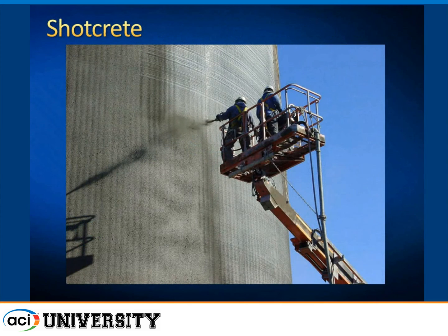In this particular case, it's being used on a tank to encase wires. But basically, Shotcrete is pneumatically conveyed concrete. You project it at a high velocity, and you don't need a form. There's no form up there to hold that concrete in place. It basically sticks in place. It's consolidated by the high impact of the Shotcrete hitting the wall, and you don't vibrate it. You wouldn't even try to vibrate it in a vertical wall like that. And we cover Shotcrete in our specification because we use it.